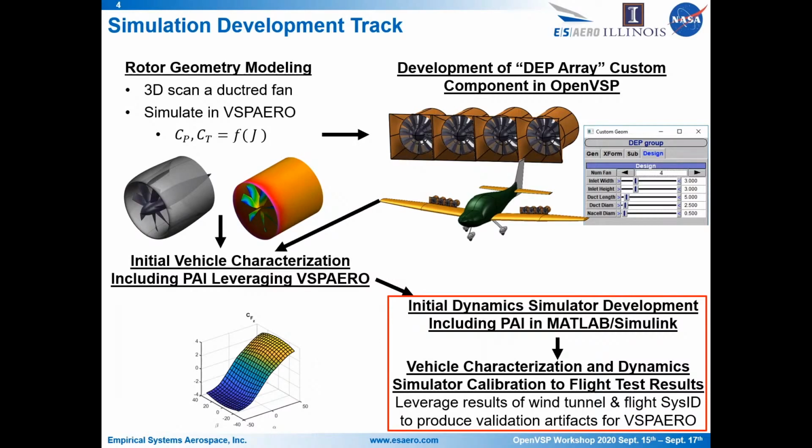On the VSPAERO side of things, last year, one of our engineers, Nick Brake, presented a status update on this program, detailing how we modeled our ducted propulsors in VSP, our development of a DEP array custom component to ease the modeling process of those propulsors geometrically, and our initial vehicle characterization, including propulsion airframe interactions using VSPAERO.